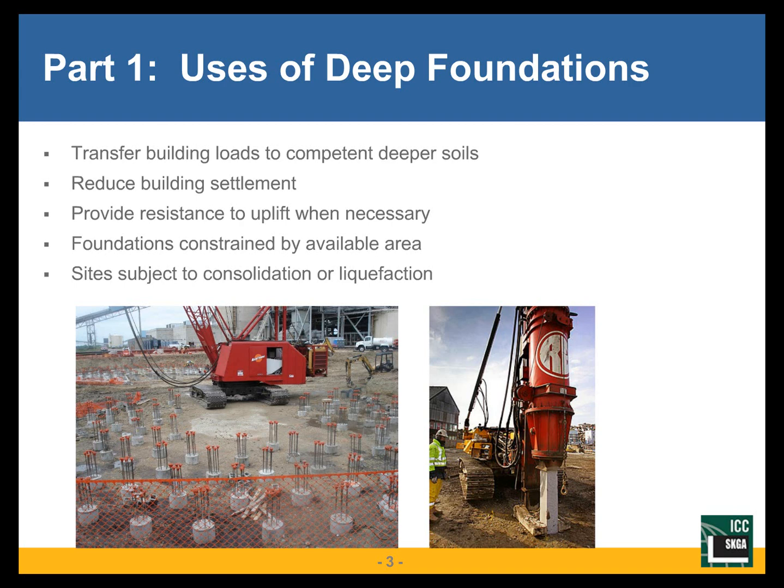In the broadest sense, deep foundations are used to transfer loads from the building down to deeper competent soils. They're used where we need to reduce building settlement. In some cases, they can be used to help us resist uplift demands due to lateral loading on buildings.